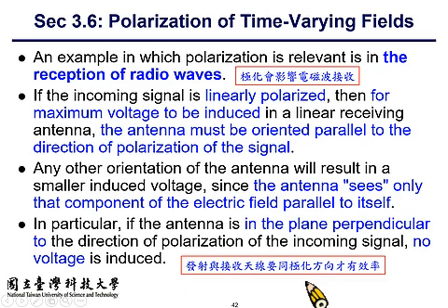How about I rotate my receiving antenna by 45 degrees? What happens to the reception? 你们听过一句话叫投降输一半，假如你把天线歪45度的话，你就是剩一半, because a 45 degrees slanted antenna can be decomposed into a vertical one and a horizontal one.